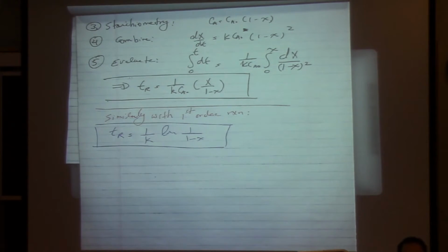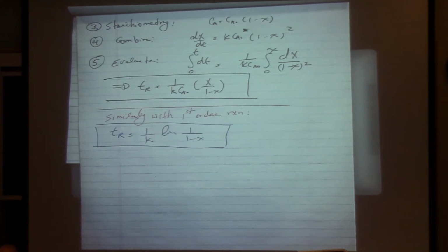As I mentioned in previous lectures, combining and taking the integration is needed just when you want to solve the integral by hand. If you use a solver like Polymath or COMSOL or other tools, you don't need to combine this equation because the software does it for you. Or if you want to use code to do the integration, like MATLAB, you need to find your final version of the equation and then use one of the integral schemes like Simpson's 3/8 rule or 1/3 rule, just to take the integration.